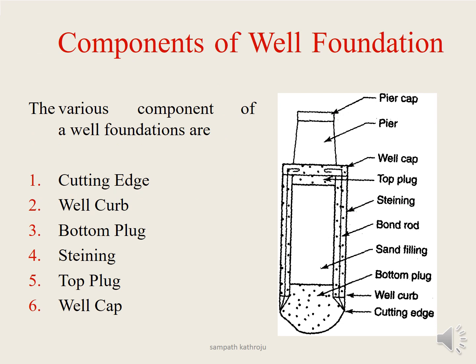We have got the components of well foundation. The various components of well foundations are shown in the figure. You can see there is the cutting edge at the bottom, then the well curb, which is the joining of the cutting edge and the steining. Then the bottom plug, which is provided after sinking to the required depth.